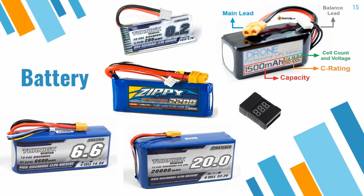Usually a battery has 2 cables, the main lead and a balance lead. The main lead is the power plug of the battery, so this one goes in the PDB, while the balance lead is capable of measuring the independent cell voltages. So if you plug this balance lead in the so-called battery alarm, that's the black box below this picture, you'll be able to display all the different cell voltages and the total voltage. Furthermore, you can set an alarm. And this alarm will beep when the battery voltage drops below a certain amount. And then you will know that you have to charge your battery, for example.